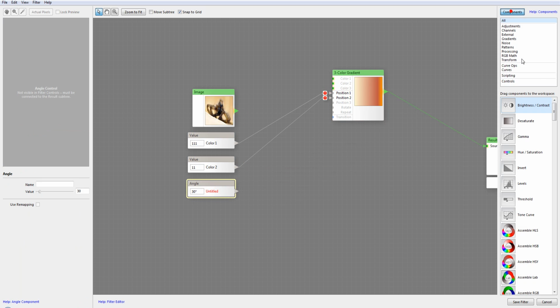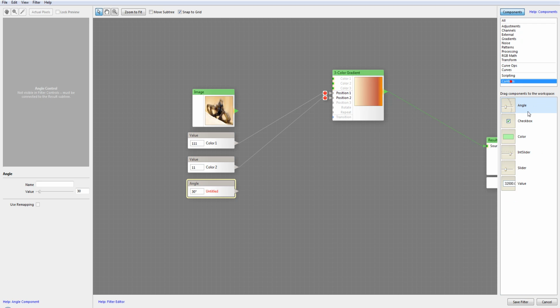Right here, we have one component control that we call angle, and this will provide values from 0 to 360 degrees for our angle. So we can connect it to rotate, and you notice when you connect, sometimes an exclamation mark appears. It means that the control is not the actual right one. It explains it's not the best way to control that input. However, it will still allow you to use this control. It just tells you that it's not the best way to do it.